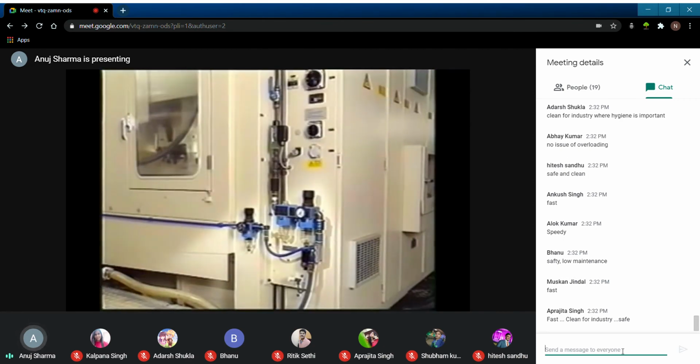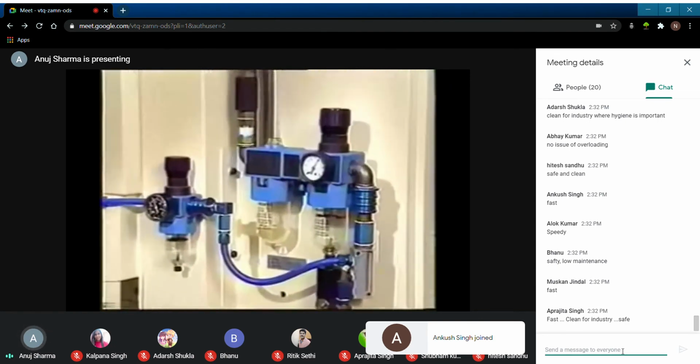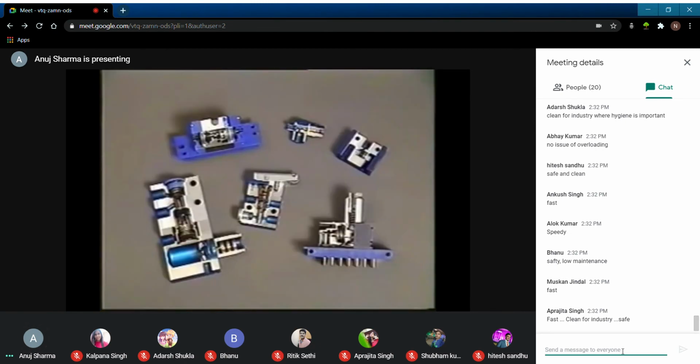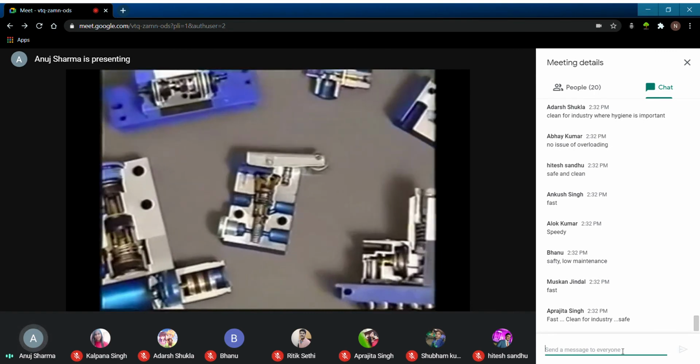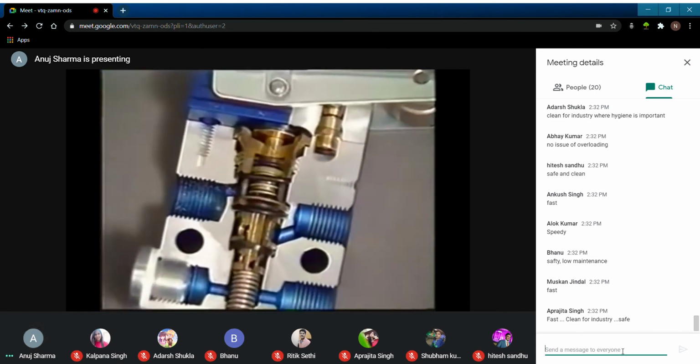In addition to the preparation of compressed air during its production, a service unit is used to prepare the air when it enters the machine circuit. These cutaways show the intricate air passages typical of pneumatic components. It's important to remove dirt and moisture that may have been picked up by the compressed air from the distribution system. Dirt could clog component air passages, and water could cause corrosion of valves and fittings.